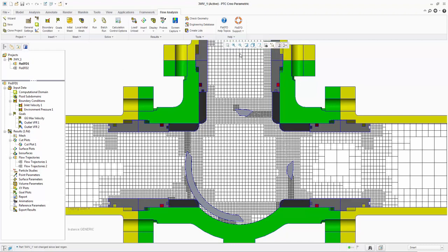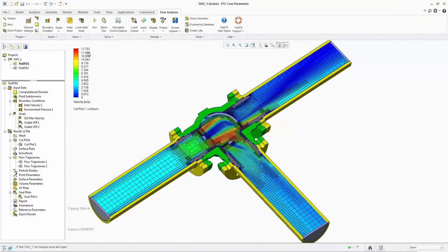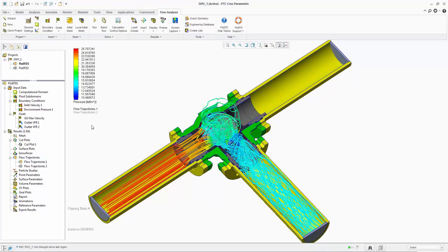One of the main benefits of having this refinement technology is that it effectively becomes a mesh sensitivity test. By running the same geometry with a series of differing meshes, we can be sure that the final result we get is accurate and mesh independent. This is very powerful and a big time-saving feature for users.